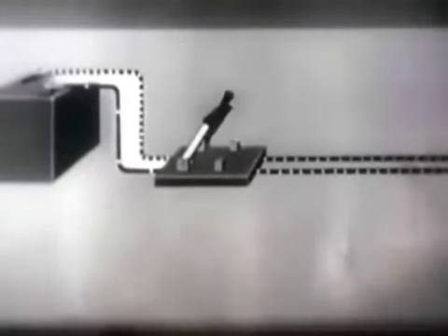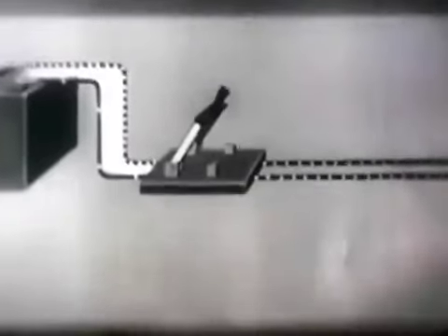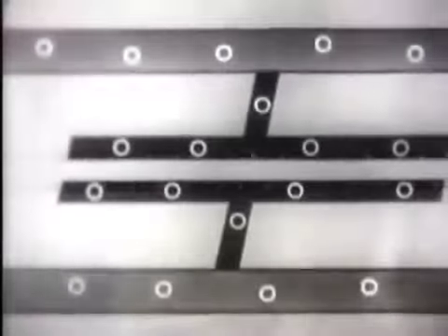Now, since this transmission line consists of two wires insulated from each other, they act in effect as a capacitor, or for that matter, as a series of minute capacitors. When we close the switch, battery current charges the beginning of the line, or the first capacitor. As current continues to flow from the battery, successive portions of the line become charged. This is a slow-motion illustration of the phenomena of electricity. Actually, this progressive charging of the line occurs almost instantaneously.